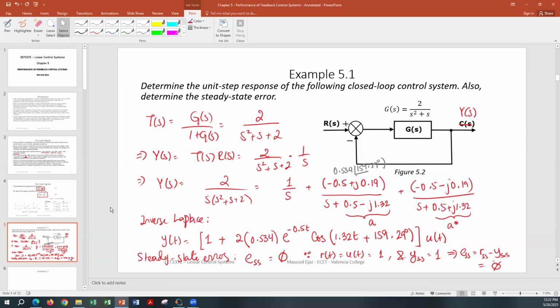So yes, 1 over 0.5 is basically the time constant of this part. It's going to increase towards 1, it's going to have a dip, and then it's going to become constant. And you want to plot it for approximately 5 time constants. The time constant is 2 seconds, 1 over 0.5. So you want to plot at least for 8 to 10 seconds with a step size of 1/100th of the time constant. That will be a good time vector to plot this.